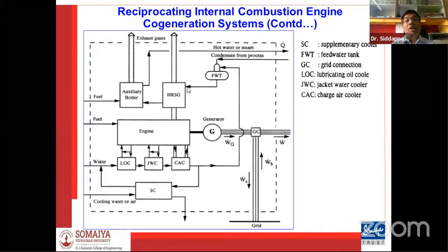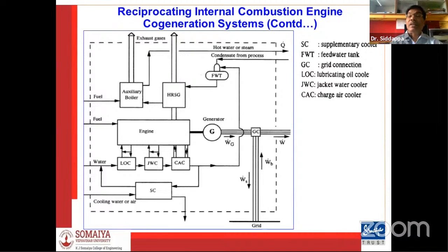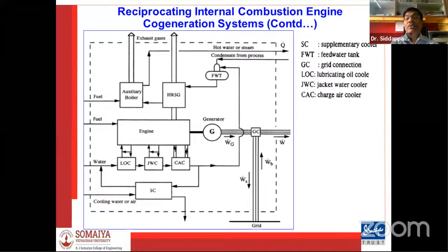This is how, at different stages, if you don't want to leave the exhaust gas to the atmosphere at high temperatures, you can use it at every stage to increase its enthalpy until its pressure goes as low as possible. Or if pressure is not the criterion and you are not using an expansion device, once you use it only in heating applications, you can use that gas until it reaches atmospheric temperature at most.